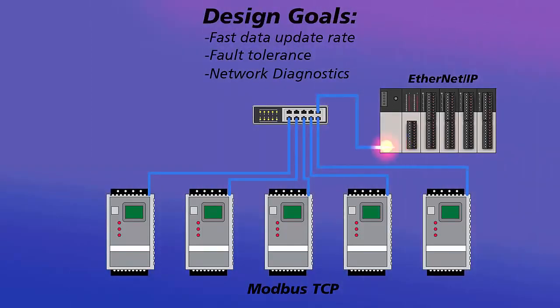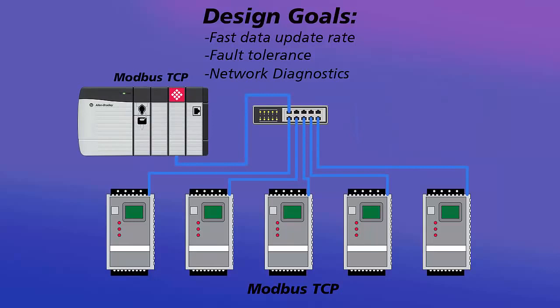This PLC can use a message instruction and some ladder code to create Modbus TCP packets via their Ethernet communication module. Using this method has some shortcomings. PLC data messages are sent at a lower priority than I/O messages and can be affected by other Ethernet messages, like if a user performs a program upload. So using this method, the communications to the drives will likely slow down periodically. For this application, a dedicated communication module that has Modbus TCP IP built in is a better solution, as it is not affected by these issues.